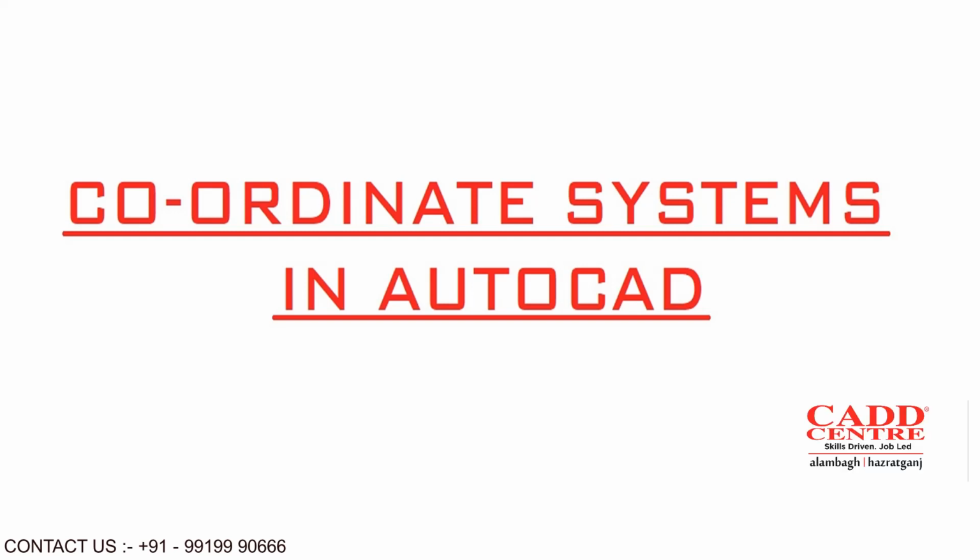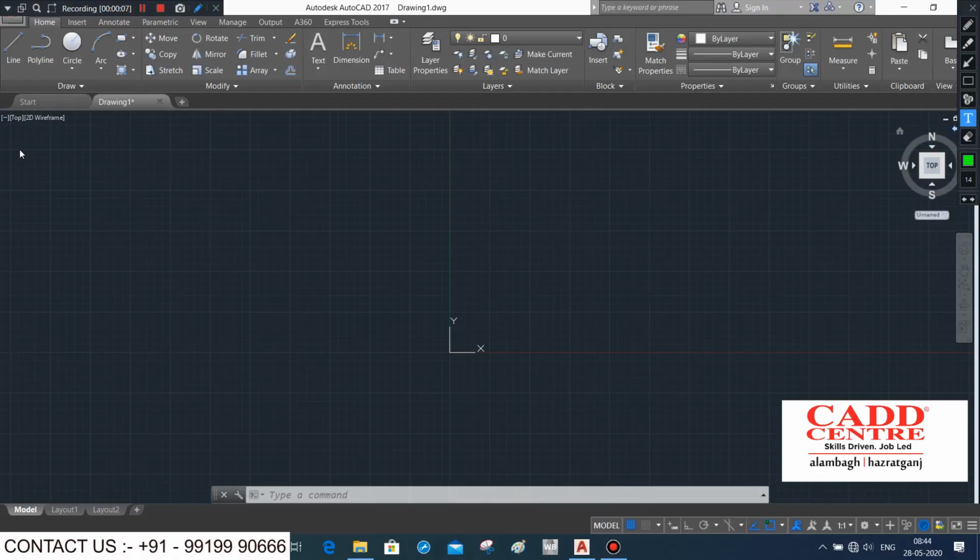In this video tutorial of AutoCAD, I am going to discuss types of coordinate systems. We have three types of coordinate systems in AutoCAD. First one is absolute coordinate system. Second one is relative rectangular coordinate system. Third one is relative polar coordinate system.